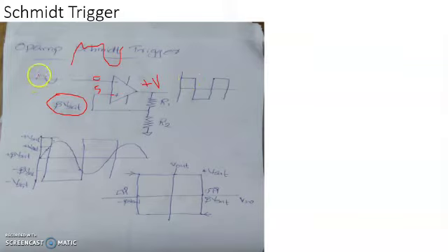And the sinusoidal voltage increases to say 1 volt, 2 volt, 3 volt, etc., as it becomes plus beta V saturation magnitude, say plus 5 volt. The very next moment, as the sinusoidal wave increases beyond 5, the inverting terminal voltage becomes more than 5 and exceeds the non-inverting terminal voltage. So the output will be switching into minus V saturation, since the voltage given to the inverting terminal of this positive reference comparator exceeds the voltage at the non-inverting terminal. So the output will switch into minus V saturation.